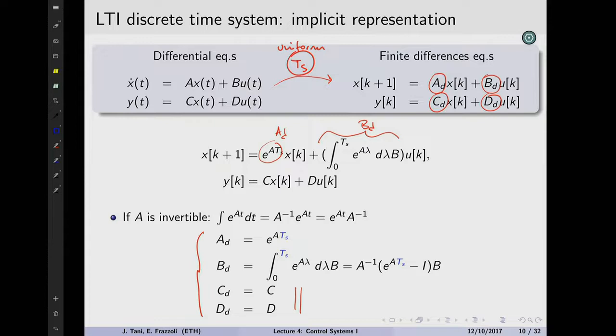But there is a fundamental result there called the sampling theorem that tells you, if you're sampling a signal, you need to sample it fast enough in order not to lose information. What does it mean to lose information? Pretend for a second that you're just given a sequence of discrete time data points. Only from those, can you reconstruct what the original signal before sampling was? If you can, you have not lost information. If you can't, then you lost information.